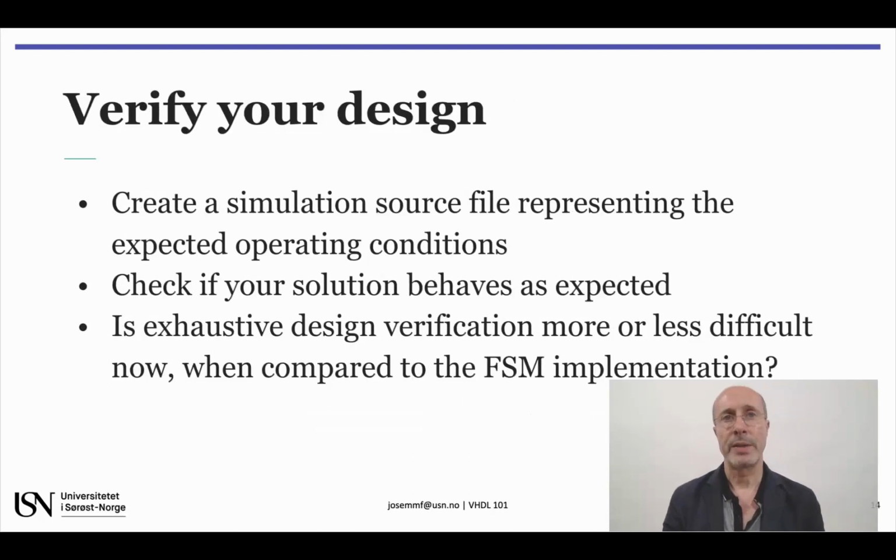The following stage is to create a simulation source file for design verification. You may use the same simulation source file created for the FSM-based implementation, since the input and output ports are exactly the same. If the simulation waveforms confirm operation as expected, you are ready to move on.